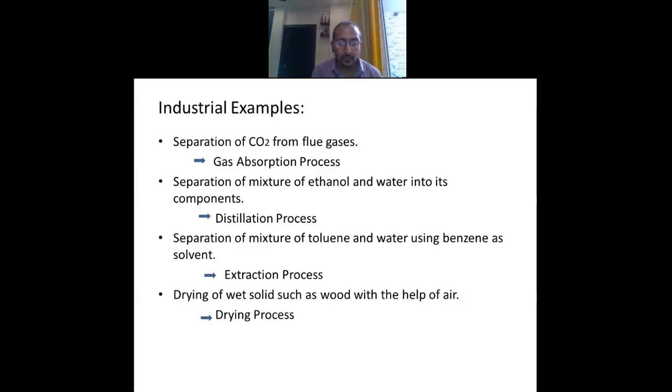When you vaporize the liquid solution, the vapor will be richer in the lighter component, the component having more vapor pressure, and in our case it is ethanol. So the vapor will be richer in ethanol than in water. Initially, our solution is 50-50% composition. Suppose 20-25% of the liquid is vaporized.